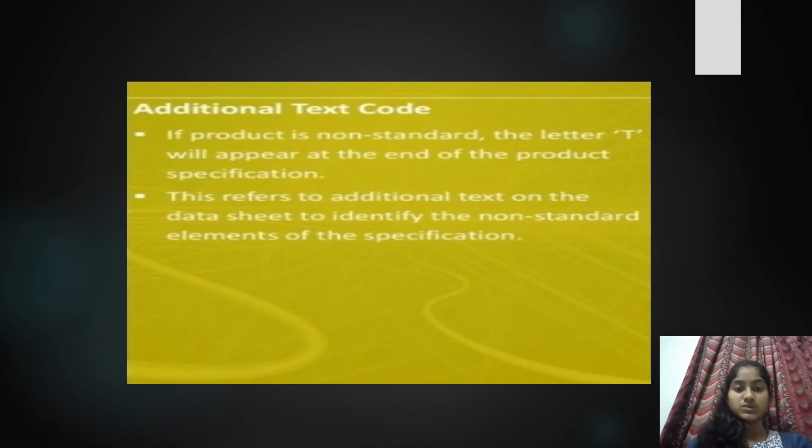Specifying VCXOs. Many VCXOs are ordered as modules from a specialist supplier of these items. It is necessary to specify them correctly to obtain the required product. When specifying a VCXO, the following parameters are normally needed: frequency, frequency stability, output, operating temperature range, deviation or pullability, and transfer function or slope polarity.